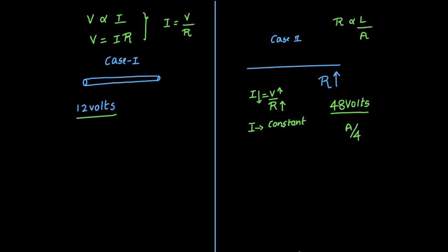So it's 1/4 of the cross-sectional area of the wire that is used in case 2. So what is the immediate advantage here? The immediate advantage is you are using less copper because you have reduced the diameter of the copper wire. So you're actually going to use less copper, so there is less wire harness there. Okay, so that's a big advantage for Tesla.